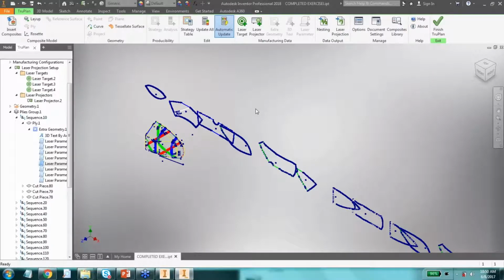TruPlan includes all the data you might need for the laser projector in order to do composite-specific projection. Anything you want to do outside the realm of composites, which might be, like you're mentioning, a frame around the tool or a footprint where the operator needs to stand, or any type of setup data, will be added on later by the TruLaser module. And the TruLaser module can pick up the ball immediately when TruPlan writes out its laser file.